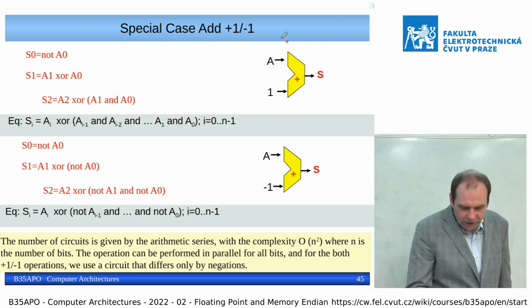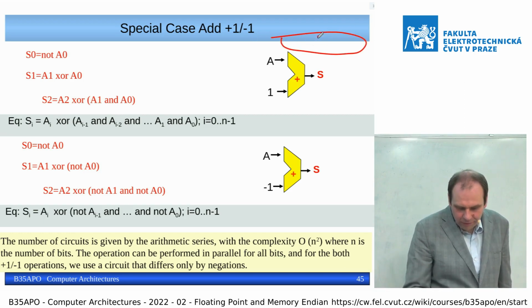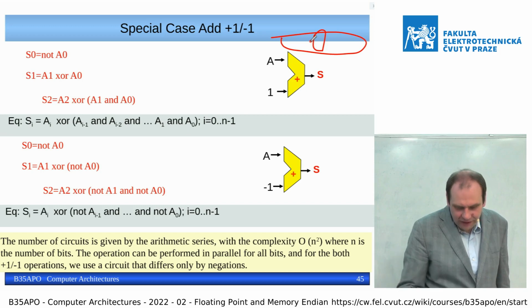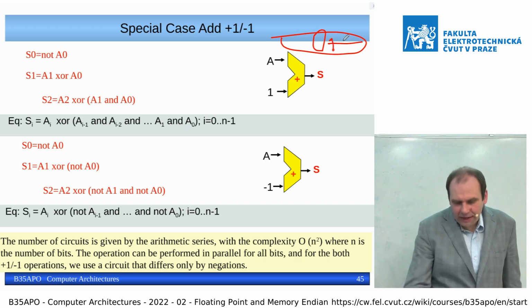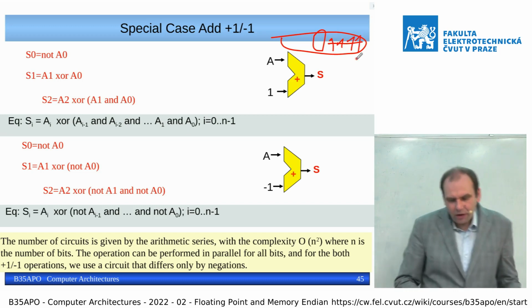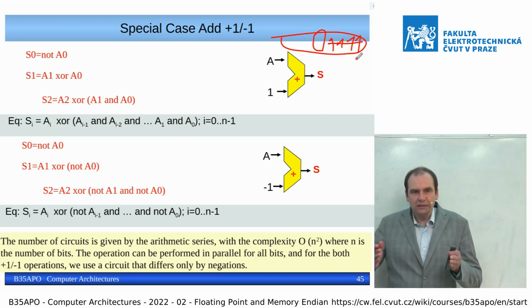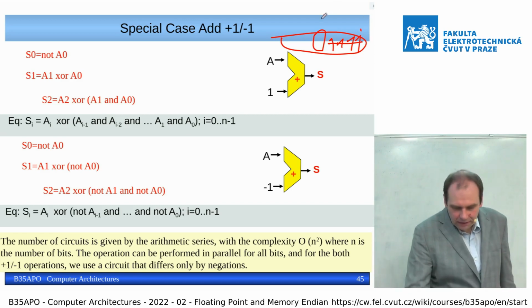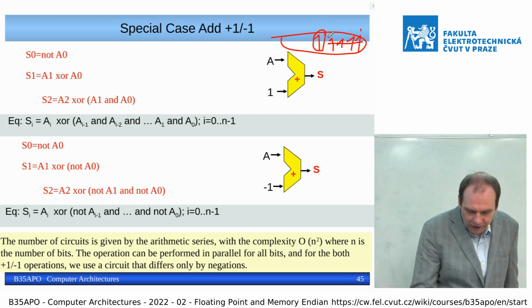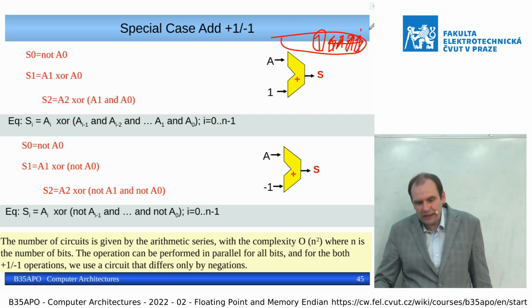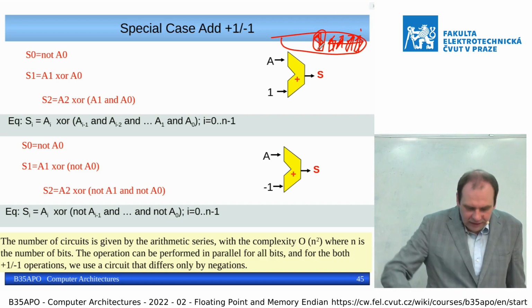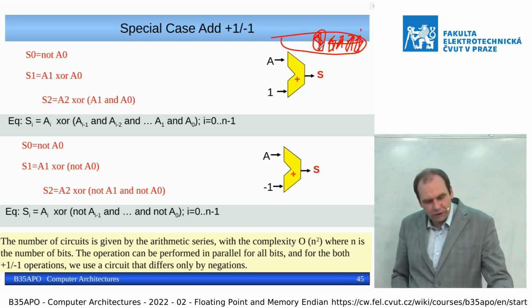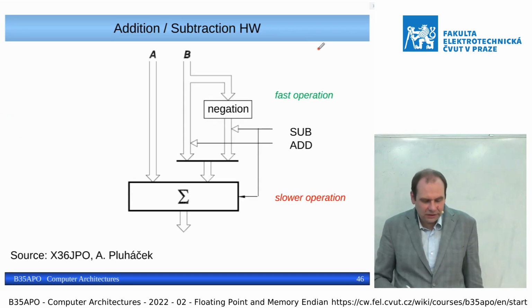For the increment, if you have some number of bits, then a given bit is flipped only if all previous bits are 1. So at the moment when all less significant bits are 1, and we want to increment, we need to flip this bit and put all the others to 0. And again, if all the others are 1 and we are at 1, then it is flipped. So the logic for the incrementer is much easier and simpler.